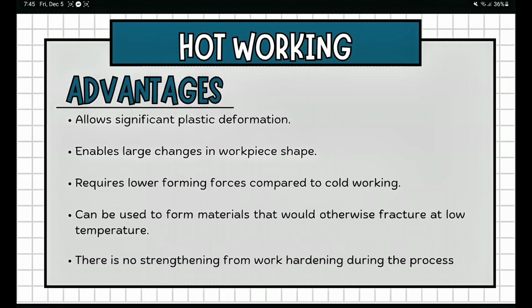So in the advantages of hot working, the first one is allows significant plastic deformation. Once the metal is heated above its recrystallization temperature, it becomes extremely soft. So this allows dramatic changes in shape without cracking.